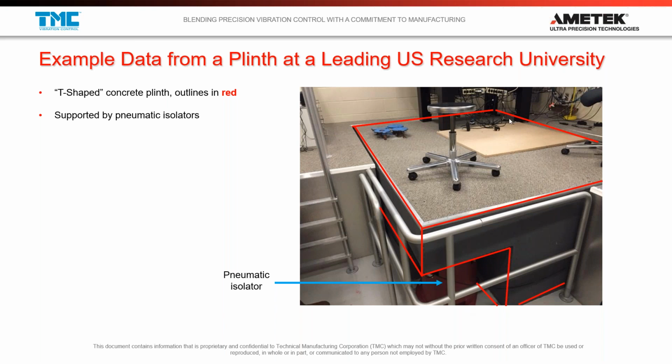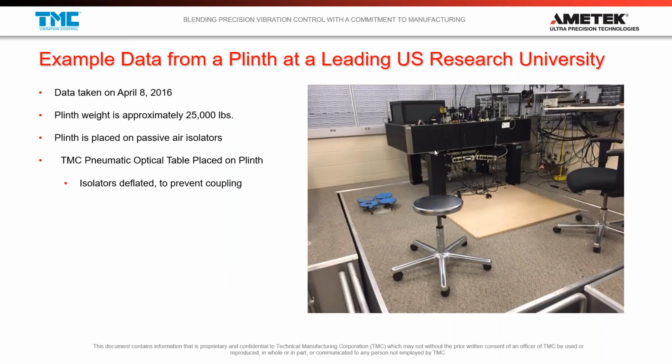When we walked in and saw this application, what we saw was that the researchers, and I'm sure you've seen this before too, had deflated the isolators inside the upper optical table. They did that because they were having a low frequency problem. They weren't having coupling problems. It's not like this table was bouncing up and down and that table was bouncing up and down and they're fighting each other and oscillating.